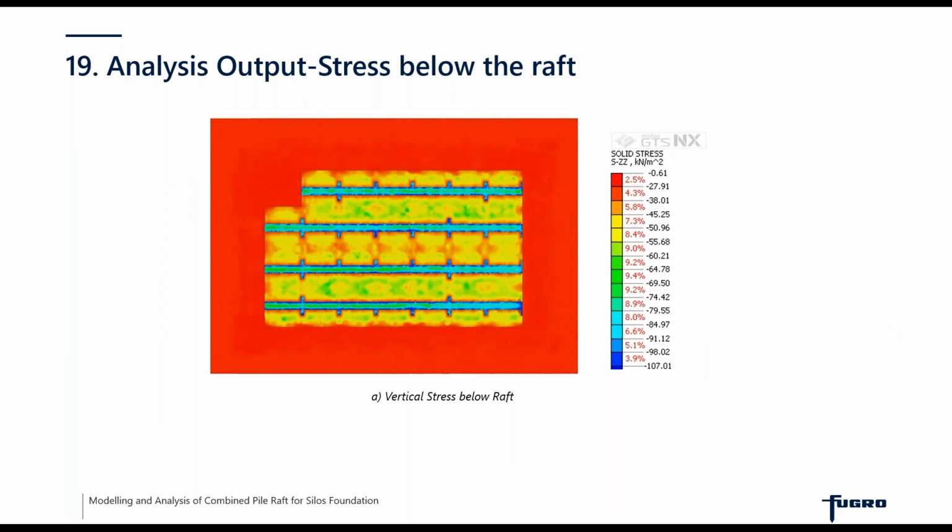You get the stress below the raft, as well as the tunnel sections which you can see. We observed a maximum stress of 108 kPa below the raft foundation.